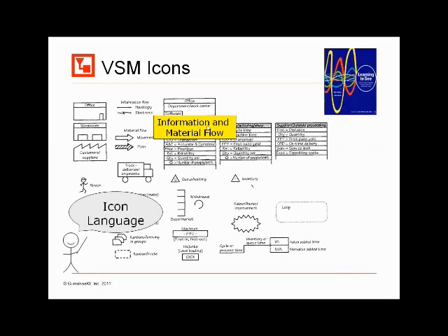There's a couple of key flows that you'll find on manufacturing maps. The first is an information flow. For example, this could be the customer sending a forecast to production control, or production control sending an email request, let's say, to their suppliers. That's all information flow. If you think about it, there could be waste in the information flow. When the customer sends that forecast, it could be sitting in an in tray and get delayed for a day or so before it gets processed. So there's transmit methods associated with information flow, and there's queues and wait times associated with that flow.